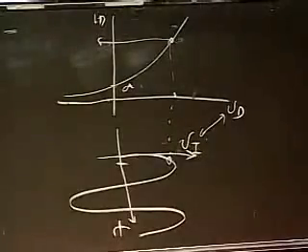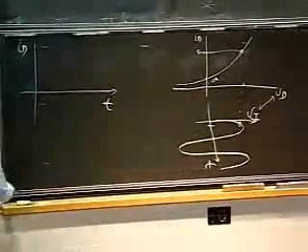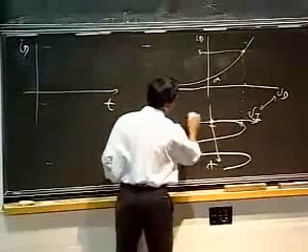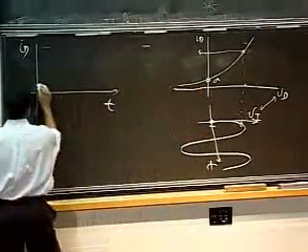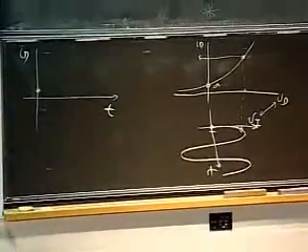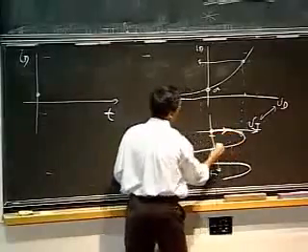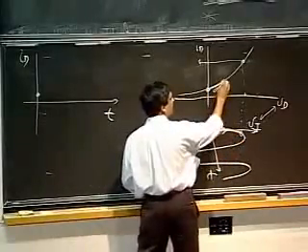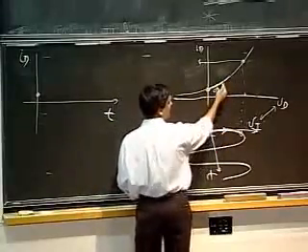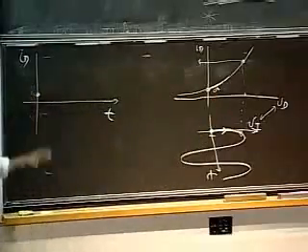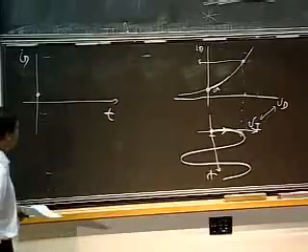Using the same artifice, I can plot the output current ID like so. So for this value, I get some current here. And so at time t0, I start here. And notice that as this signal moves up here, I can find out the corresponding values of ID by looking at where a straight line from here intersects here and plotting the values here. I had a nice little graphical animation to show you this. Hopefully the laptop will work tomorrow and we can check that.